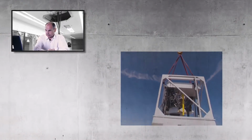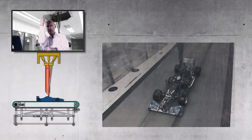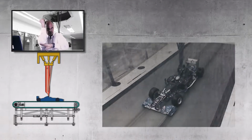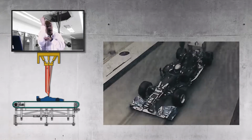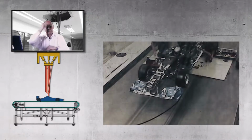The hexapod has certain advantages structurally. It's quite stiff. It allows you to do most of your motion from above. So with a hexapod, you control the roll by moving the hexapod sideways like this. You control pitch by moving the top of the arm fore and aft. Yaw is done lower down. You can do yaw from literally within the model. On ours, we have the yaw point a little bit higher up, and we yaw it from a point here. So most of the model support is aerodynamically aligned with the airflow, and only the bottom part moves the model.